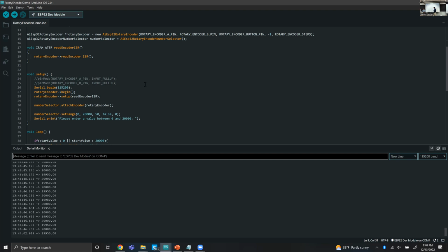If this doesn't have the resolution, you'll say that this device's resolution is this many steps in RPM. It could be every 1 RPM or every 2 RPM. They have to adjust their test. They can interpolate, extrapolate, find out the data, right? If choosing a different sensor helps you improve the resolution, you should do that. If you're limited, then you will write the instruction for them. If you couldn't fix it in the mapping, because this is basically voltage reading, right?